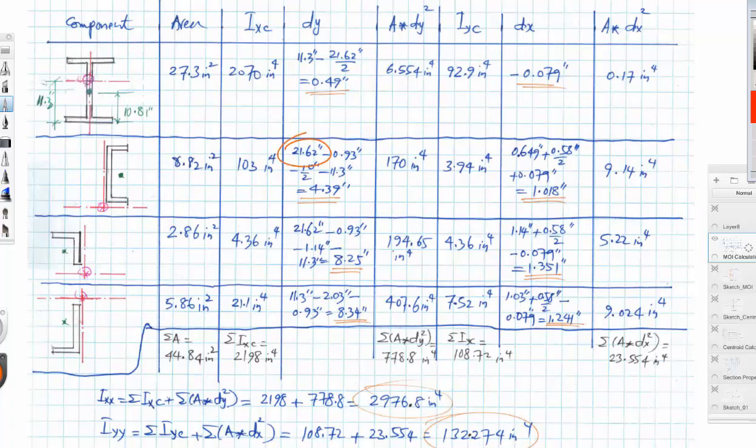The depth, the entire depth, that is for the beam, the flange thickness, and then half of the depth of the channel, like I said, and then minus the y bar, the distance from the bottom to the centroid. And while we're on it, same goes here. This is the entire depth. This is the flange of the beam, and this is the y or x bar because it's equileg, and then this is the y bar.